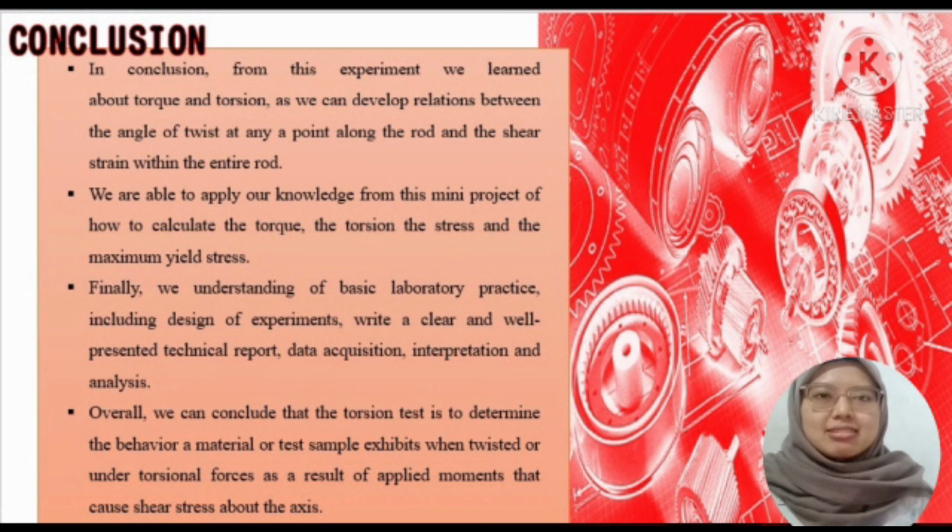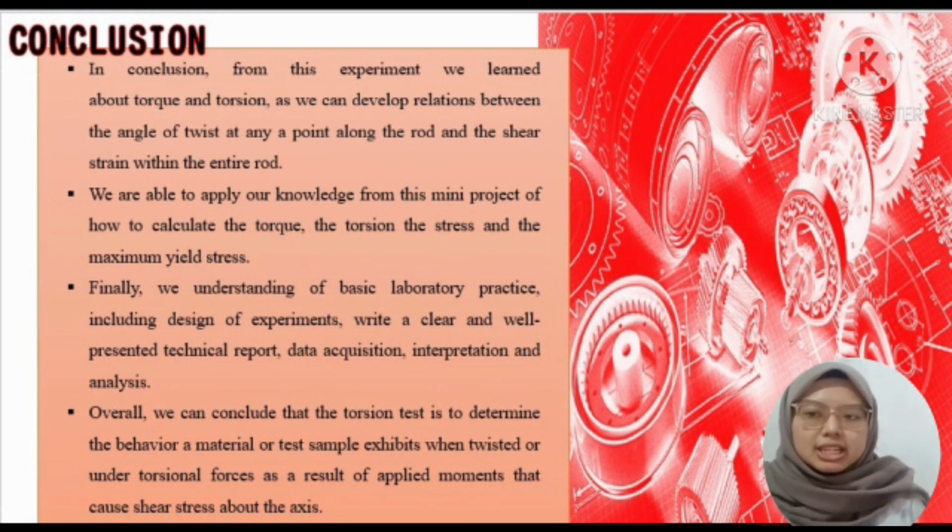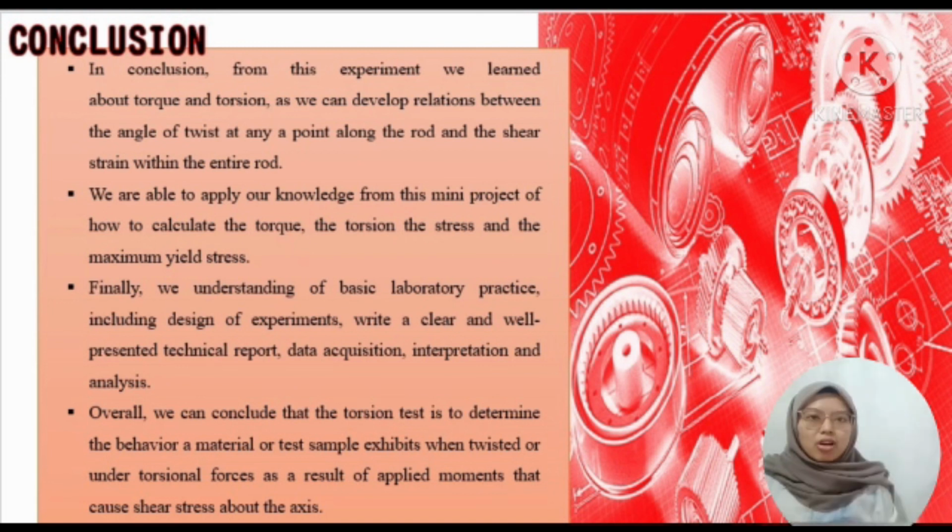Okay, finally, let's talk about conclusion. In conclusion, from this experiment, we learn about torque and torsion, as we can develop relation between the angle and the shear strain. Okay, then we are able to apply our knowledge to calculate the torque and torsions, the stress and the maximum yield stress. Finally, we are understanding of basic laboratory practice. Overall, what I can conclude, the torsion test is to determine the behavior of material or test sample when faced or under torsional stress as a result of applied moment that can cause shear strain upon the